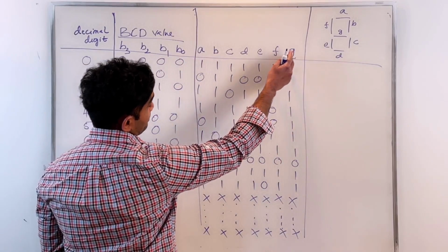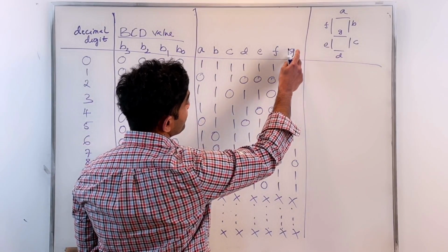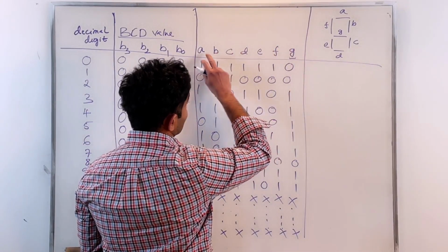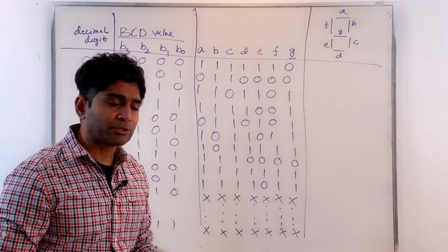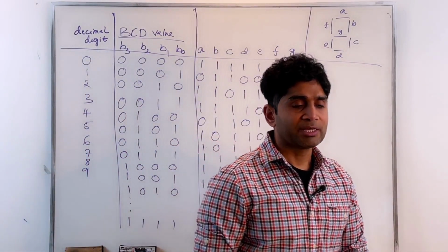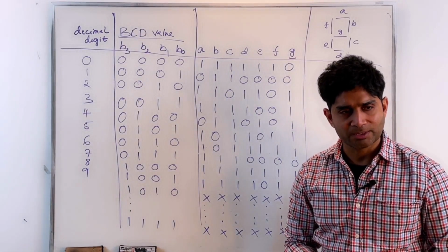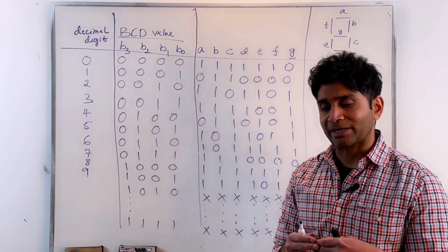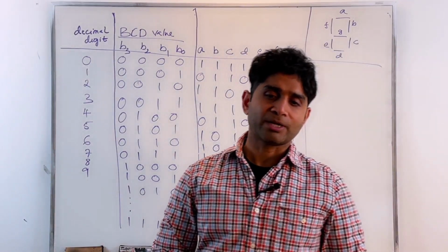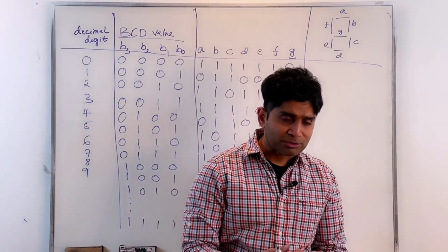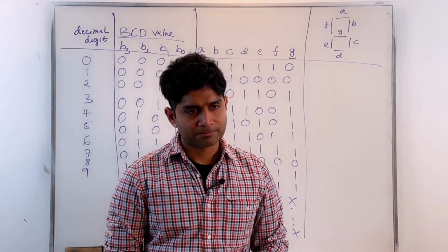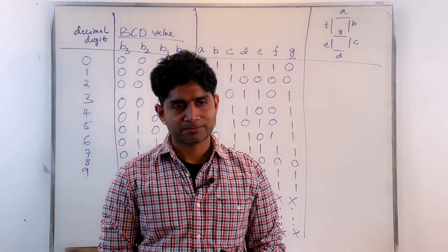Like, can there be any product terms common to F and G implementation or ABC implementation? I would like to reuse those product terms. That way I can reduce the redundancy in my circuit, and reduce the power consumption and complexity. Okay, does it make sense?